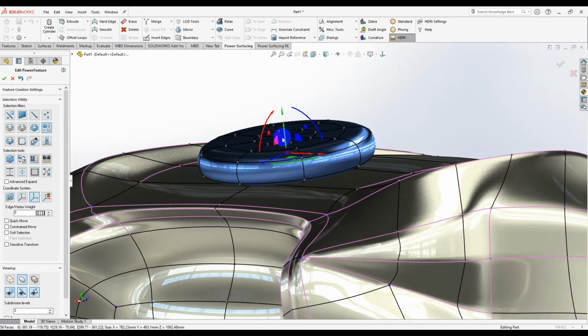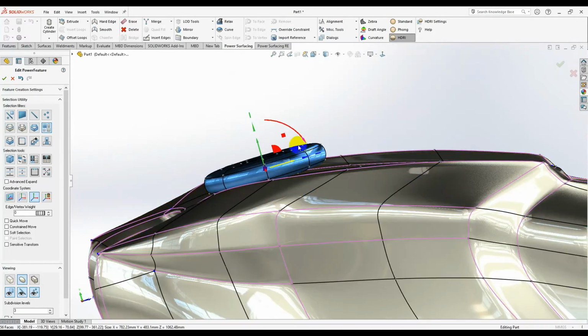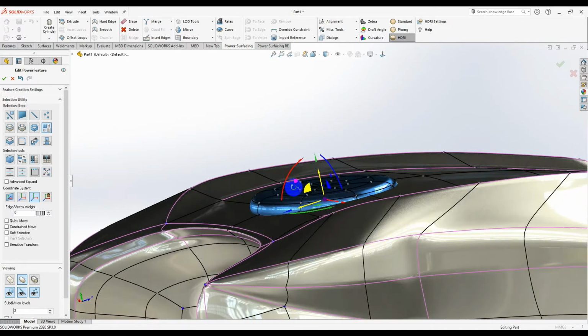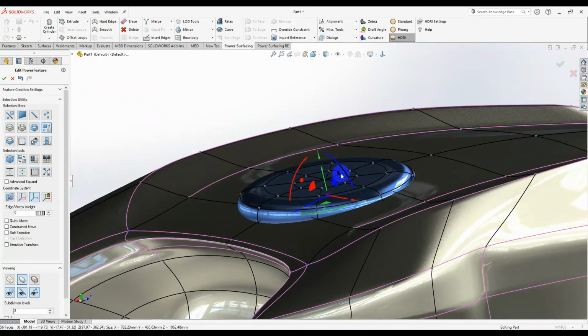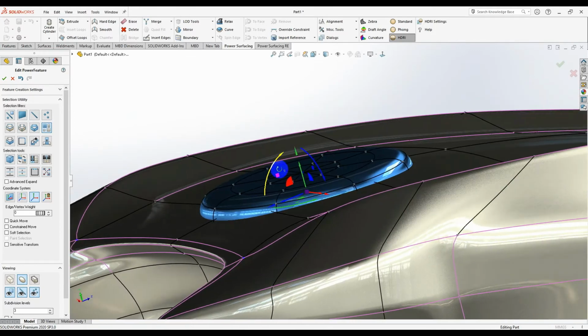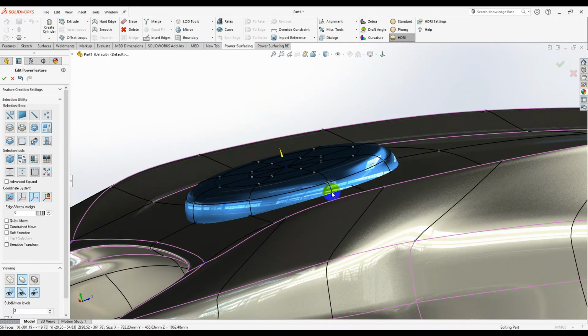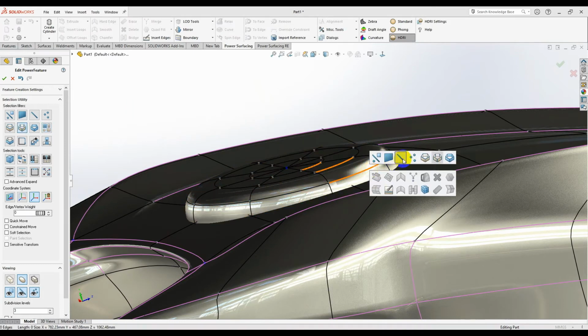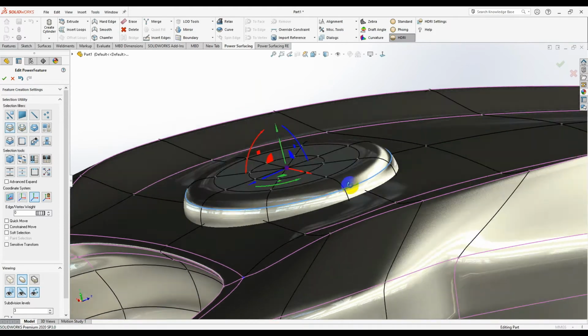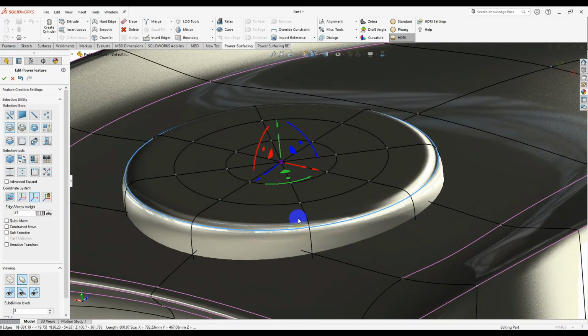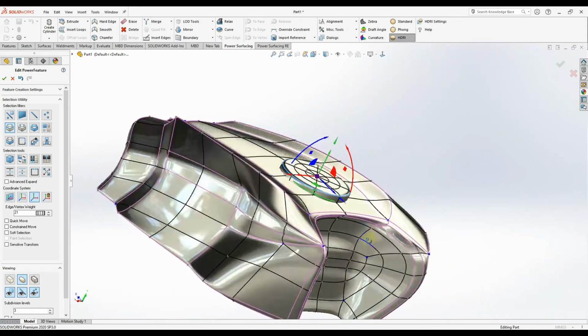Now I'm going to rotate it a little like that and just down until it's merged with the tank body. Let's stretch it up a little, and you can easily use the switch to edge loop selection, select this loop and just crease it. Let's make it 22 creasing. Okay.